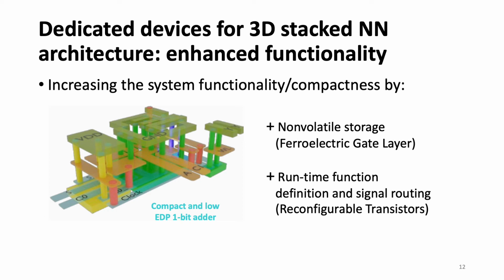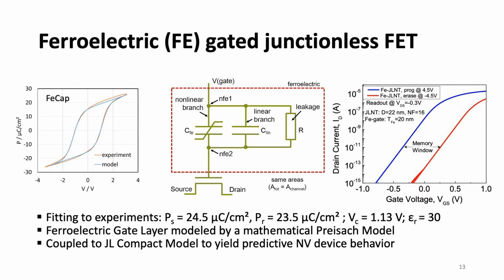Here, on the left side, a 3D layout sketch of a compact and low-energy 1-bit adder is shown, which incorporates this non-volatile storage. The second additional element are reconfigurable transistors with electrically controllable polarity. First, let's start with our approach to predictively model the ferroelectric FET behavior within our junctionless nanowire technology.